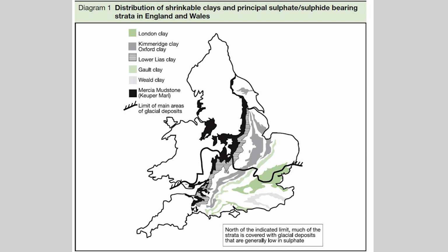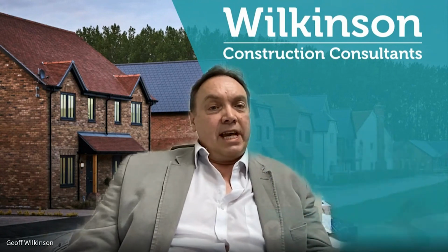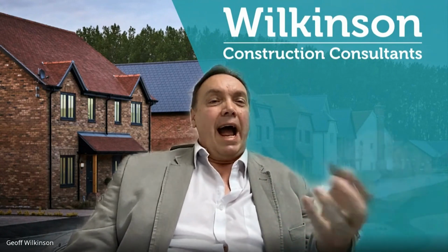Even in the approved document itself, it gives you a very brief generalized map of the UK, identifying things, for example, like clay soils that have a high shrinkability. So you can get quite a lot of information without necessarily having got someone to go to the site and start sampling the soil itself. If that first desktop study starts to show that we might have some problems on this site, then absolutely you need to be doing a more detailed investigation.